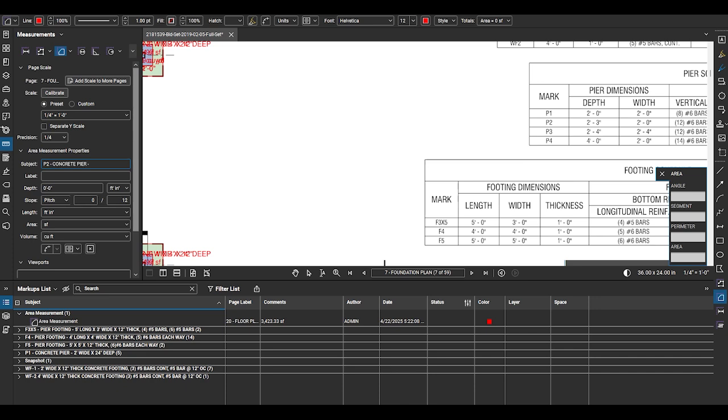Repeat the process for P2 concrete piers. I didn't spend any time in this video explaining or even looking at the reasons for the multiple sizes of piers, but it is related to bearing capacity and size and height of the steel columns that sit on them. There was a schedule in the first couple pages with a lot of details on elevations of all the various structural columns.